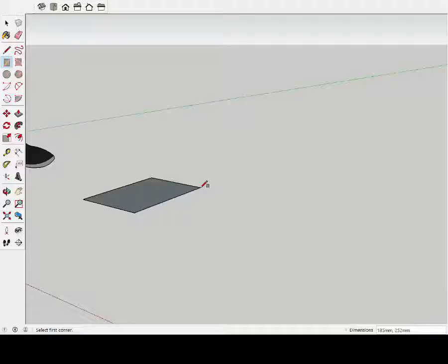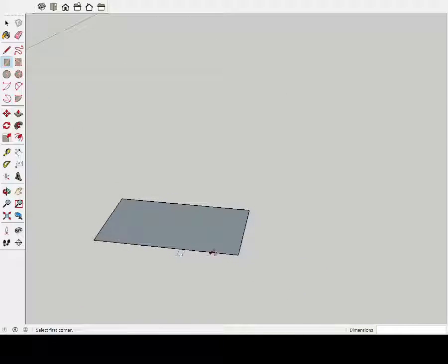So the sizes would be 340 on this particular one, comma 180. I am of course working in millimeters, and that's what it's going to make it. I can check these measurements by using the dimension tool and clicking to the corners of this, which I'd like you to do as well, to put measurements on there.